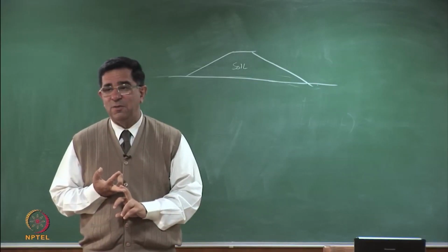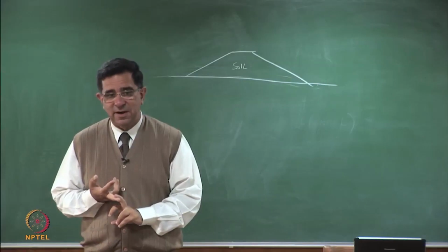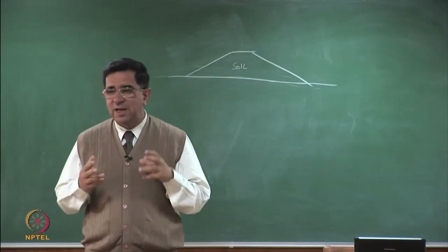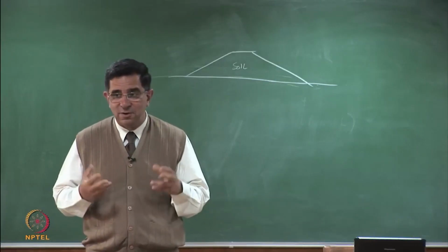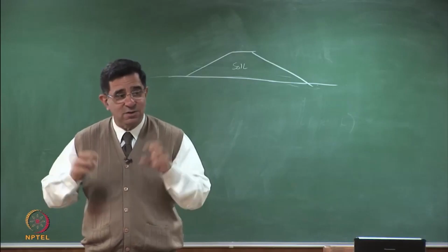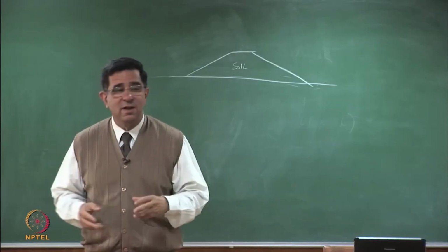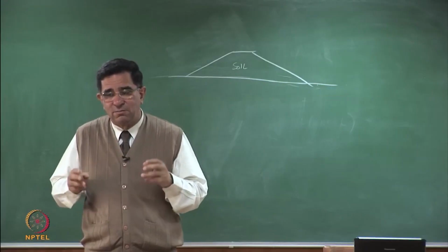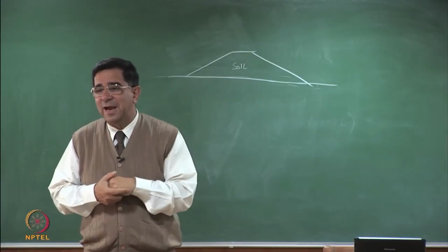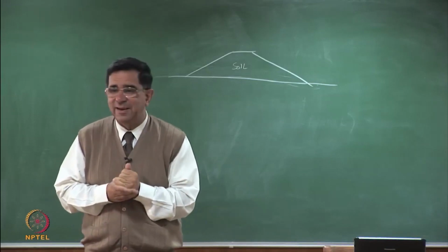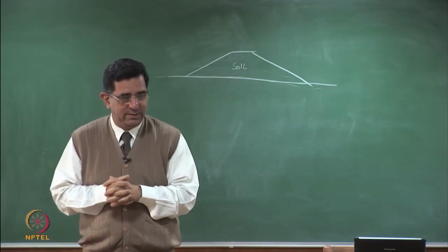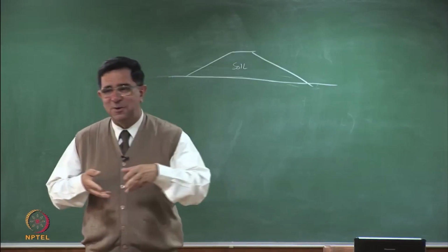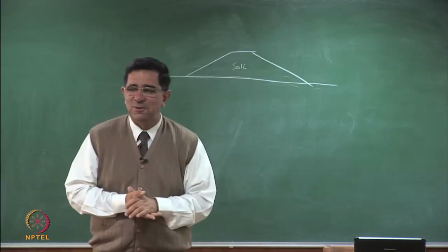What is the C dash for normally consolidated clays? Effective cohesion intercept. So the bulk of the data shows that C dash in normally consolidated clays is 0. C can be there, any value, high value, stiff clay, from UC test, from UU test. But remember, C dash for saturated soils tends to be 0. So quickly, what is the C dash that we would get in waste? If I get C dash 0 in clays, I get C dash 0 in sands and gravel, obviously C dash would be 0 in silts.